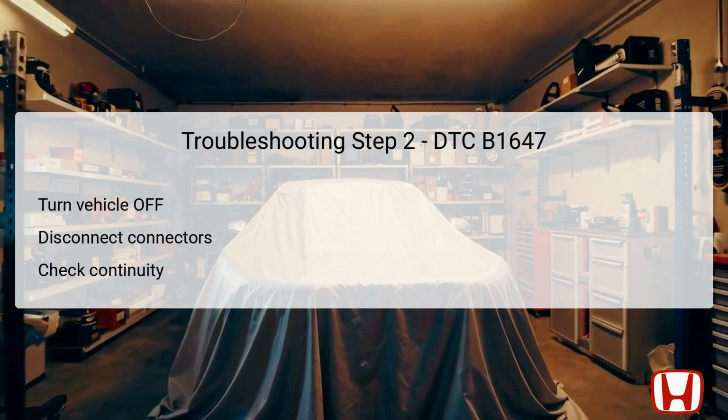The test must be conducted under the vehicle off-lock condition, allowing for a clear reading of the electrical flow. This analysis helps to identify if there is a short to ground in the wiring that needs to be repaired. Confirming continuity here is crucial to diagnosing the short accurately based on the test results before progressing to subsequent troubleshooting steps.